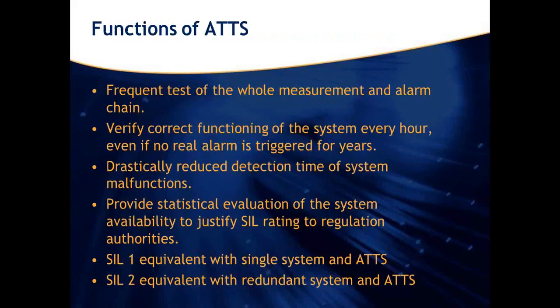So in summary, the functions of the ATTS are to enable frequent tests of the measurement and alarm chain. That enables the verification of the correct functioning of the system every hour, even when there are no real alarms triggered for many years. Therefore, this drastically reduces the detection time of system malfunction, and they can also provide a statistical evaluation of the system availability to justify a given SIL rating to the regulation authorities.